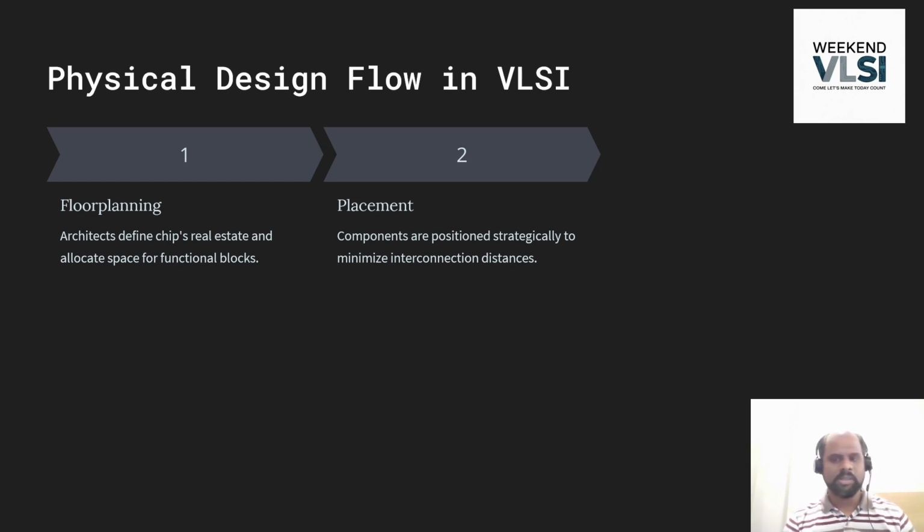Then the next step in placement is optimization. Maybe you do buffering for the data path, or you may do sizing of those logic cells or pin swapping, etc. This is called optimization. We do optimization for a couple of reasons.